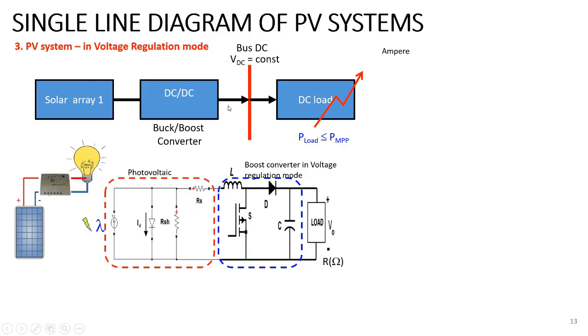Unfortunately, the disadvantage of the P&O algorithm is that it causes the voltage on the bus DC to vary. And thus, the electrical equipment used as the load in this circuit, in general, cannot work stably at its normal condition, since the bus DC voltage following the MPPT rule is usually deviated from its normal voltage.